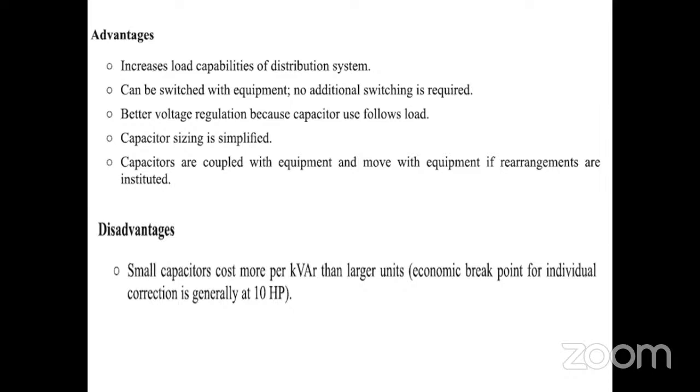When we switch on the motor, the capacitor will also get switched on. No additional switching is required. Better voltage regulation because capacitor use follows load. Capacitor sizing is simplified. Capacitors are coupled with the equipment and move with the equipment if rearrangements are instituted.